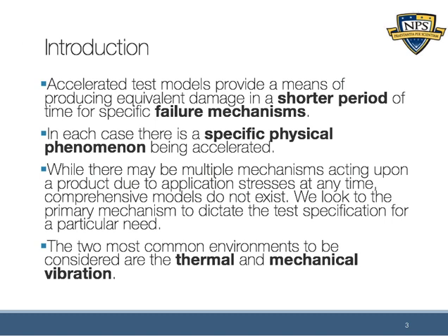It's important to understand there is usually a specific physical phenomena that creates a failure mechanism, and it's specifically that one that's being accelerated. And the third bullet point here is related, and that basically says that there's not one model that looks at all the failure mechanisms, all these causes of a failure, all at one time. And so we have to look at them one at a time.